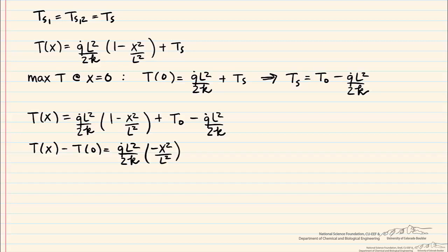So note we don't have to know the surface temperature, as long as we know the centerline temperature, to find a temperature at any x within the plane wall.